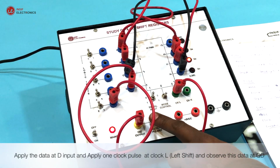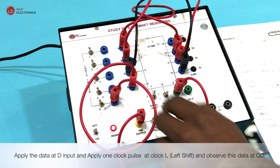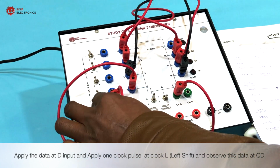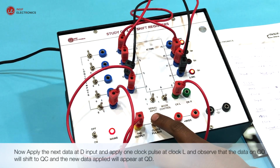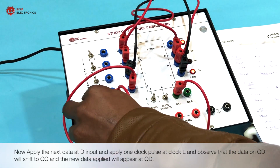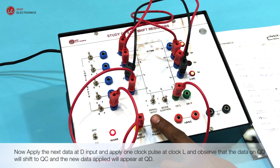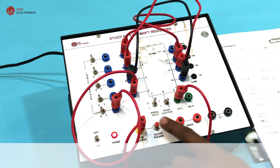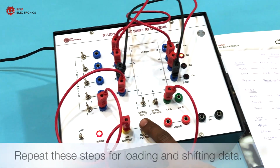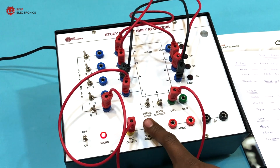Apply the data at D input, and apply 1 clock pulse, at clock L, left shift, and observe this data at QD. Now, apply the next data at D input, and apply 1 clock pulse at clock L, and observe that the data on QD will shift to QC, and the new data applied will appear at QD. Repeat these steps for loading and shifting data.